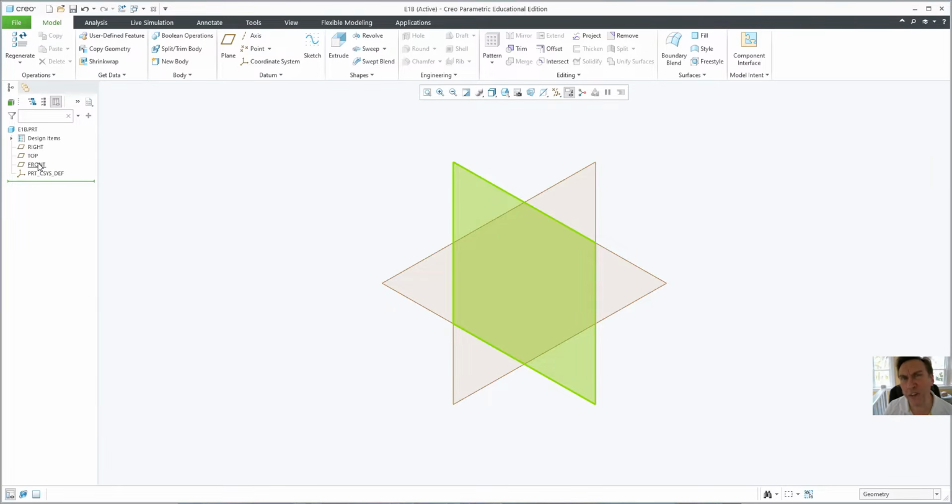Later on, once we have models, anything that's flat on a surface, you can sketch on. But until now, this is where we have to start. And they all converge on a centralized origin, the CSYS inside here. And that's going to be our anchor point. That's the zero marker in space. So 0x, 0y, 0z. And technically, you don't want to move it, or it gives you the ability to create additional ones if you need them, but we don't have to worry about that so much these days.